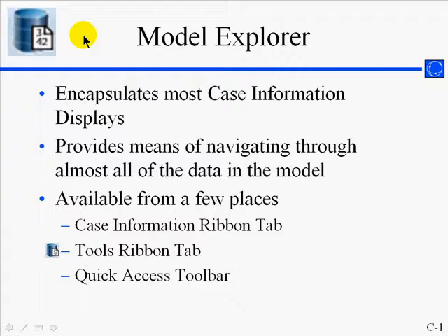In this session, we will learn how to use the Model Explorer and the case information displays in PowerWorld Simulator to view and edit text-based data. The Model Explorer is a container that encapsulates most of the case information displays. A couple of exceptions include the area zone owner filters, which we looked at in a previous session, and limit monitoring settings, which we will look at in a future session.